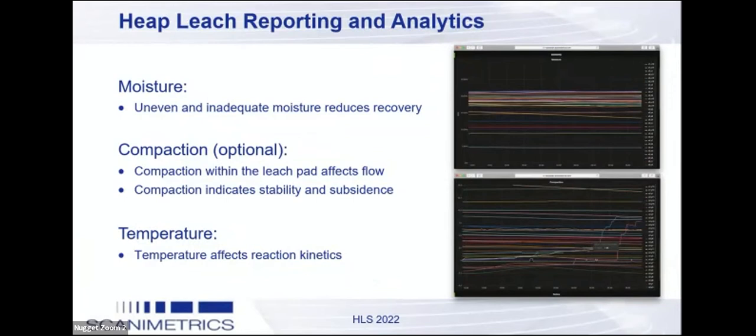Here's some examples of some of the measurements of the data. The upper graph there shows the moisture measurements. Some of these sensors were decreasing in moisture content. The lower one is actually compaction measurements, and some of those you can see there are sort of step changes happening in the compaction. Those particular ones are during backfill. So you're seeing every time there's more backfill put on the leach pad, you're seeing step changes in the compaction